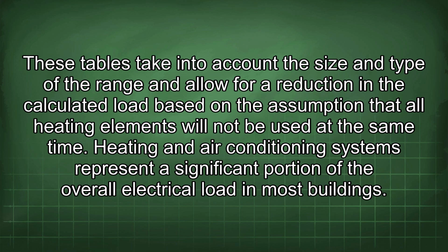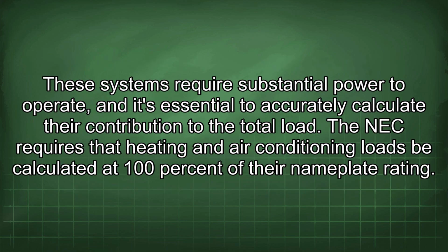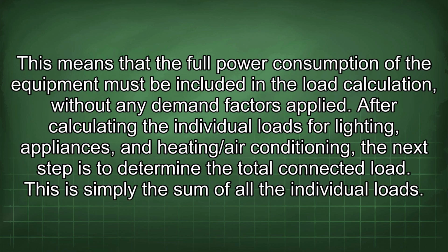Heating and air conditioning systems represent a significant portion of the overall electrical load in most buildings. These systems require substantial power to operate, and it's essential to accurately calculate their contribution to the total load. The NEC requires that heating and air conditioning loads be calculated at 100% of their nameplate rating. This means that the full power consumption of the equipment must be included in a load calculation without any demand